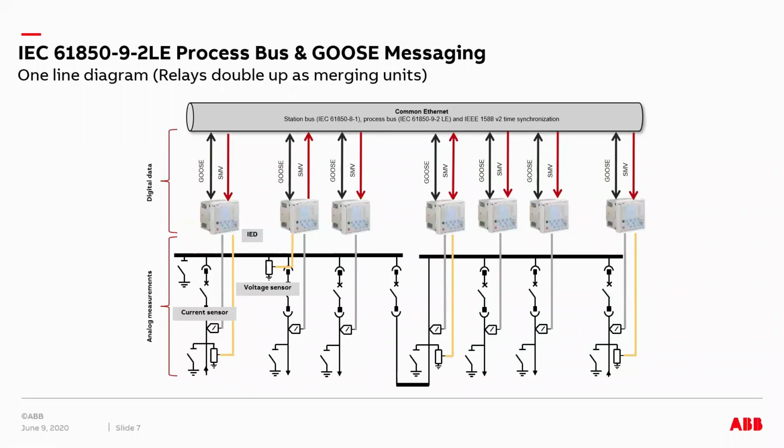Anything of that kind can be achieved using GOOSE message sharing, where one relay can send its trip status, pickup status, or I/O status to other relays, which subscribe to those signals and take action based upon that. So we totally eliminate inter-panel wiring by using GOOSE messages.